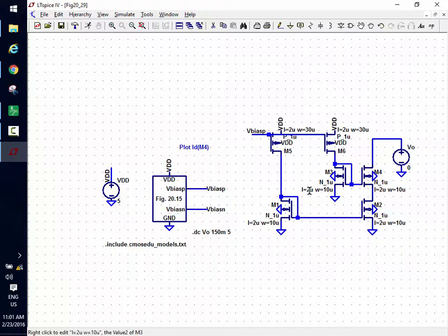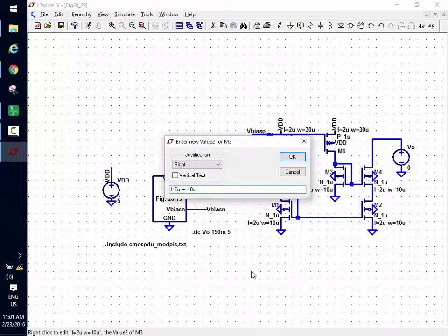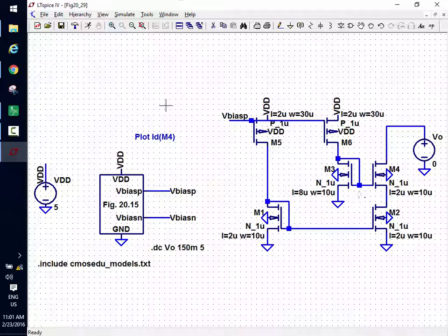Okay. And then let's go over here. If I make this 1/8 or 1/4, I make the L larger, and I hit fit. Tell me what that does to the voltage here. If I make that longer L, what happens to the voltage right here? Okay, forget the circuit for a moment. Let me just pretend we're in the supermarket and I'm asking you a CMOS question because you need your brain flexed. If I keep the current through a MOSFET constant and I increase the length, what happens to its VGS?